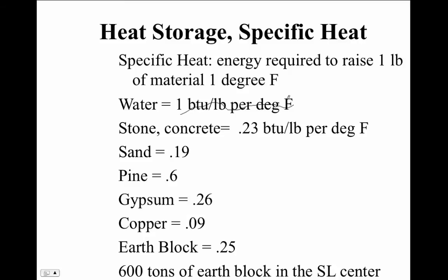So that's the specific heat of water. But for stone and concrete, it's 2/3 of a BTU per pound per degree Fahrenheit. So if you put in just 2/3 of a BTU, you'll raise that material up 1 degree Fahrenheit. And if you cool it 1 degree Fahrenheit, you'll only get back 2/3 of a BTU.